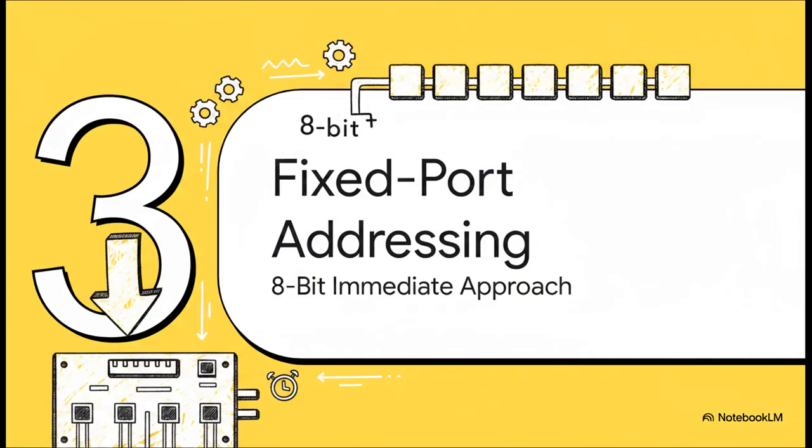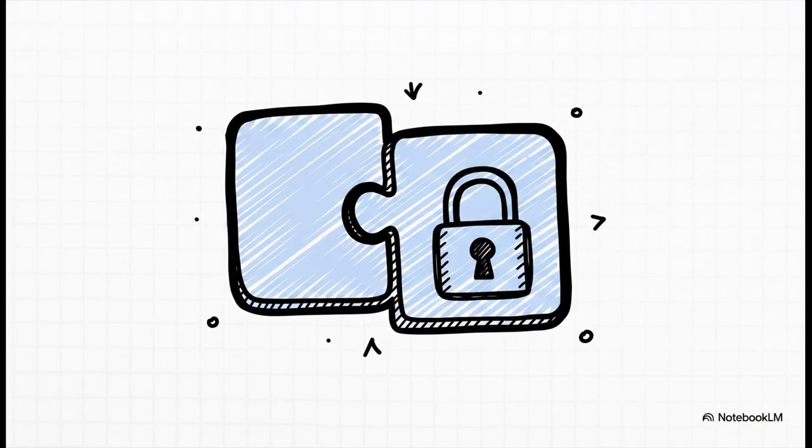Section 3. Fixed Port Addressing Explained, the 8-bit immediate approach. Let's look at how this builds our first addressing method. This is where the port number is just hard-coded right into the instruction syntax. We call this fixed port addressing. It allows data transfer using an 8-bit I/O port address. And it's called fixed because that 8-bit port number is completely immutable. It's attached directly to the opcode, just like immediate addressing. Once you compile it, boom, that port is set in stone.